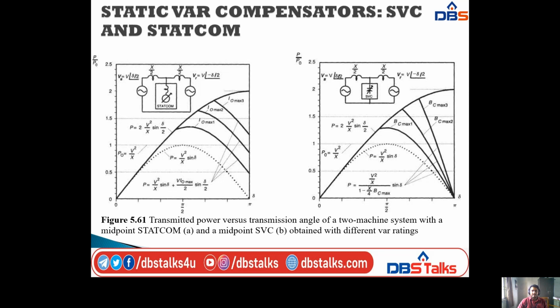Here we have P equal to V squared by X, and P equal to 2V squared by X into sin delta by 2. These are at I_0 maximum 1, I_0 maximum 2 and I_0 maximum 3. Coming to the SVC, I am also taking different curves, but here I am taking B_C maximum 1, B_C maximum 2 and B_C maximum 3. Here P equal to V squared by X into sin delta, and P_0 equal to V squared by X, and P_0 equal to 2 into V squared by X into sin delta by 2. Like this we are drawing the curves.